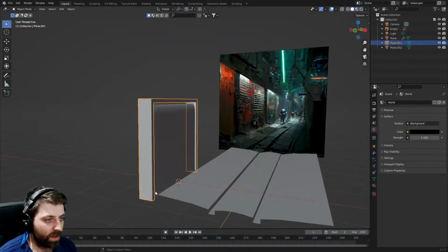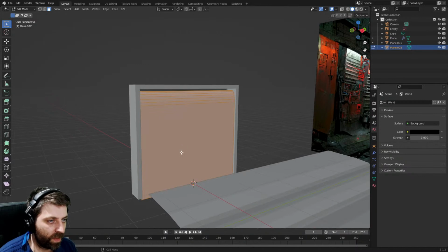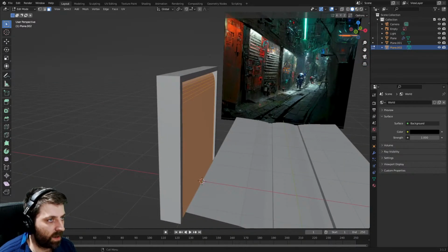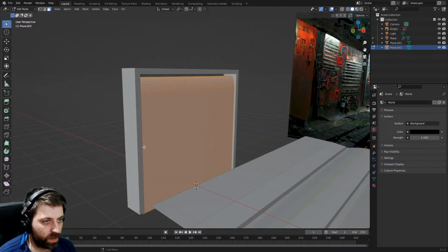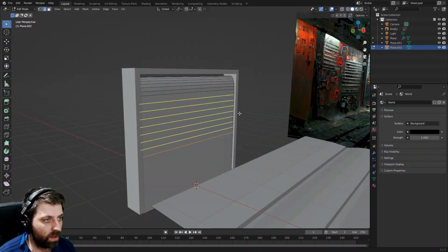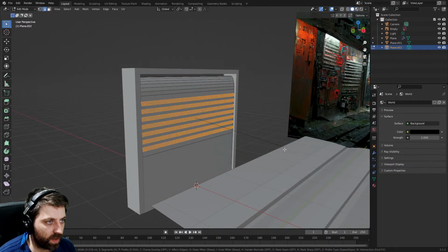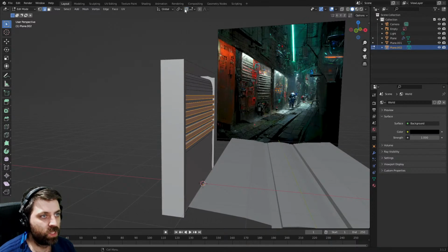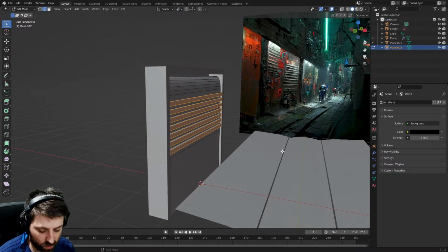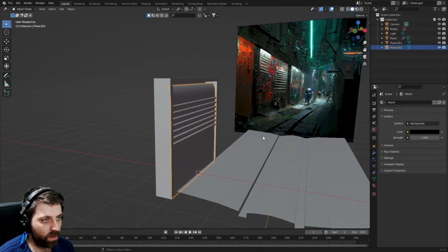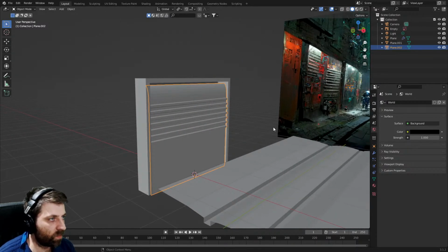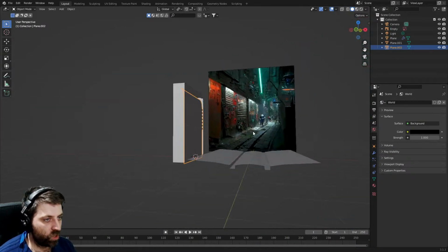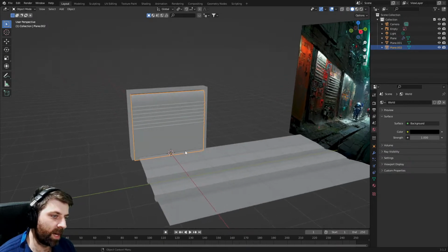Okay, so I'm pretty happy with how that's turned out. Let's go ahead and maybe create these riffles. So I'm going to put an edge loop through here. Let's do that. Control B to do a bevel. And then from here, I'm just going to go E to extrude. Come up to the top and say the medium point individual origins. And so we've kind of got these grates here. I think that looks pretty cool. I'm fairly chuffed with that.